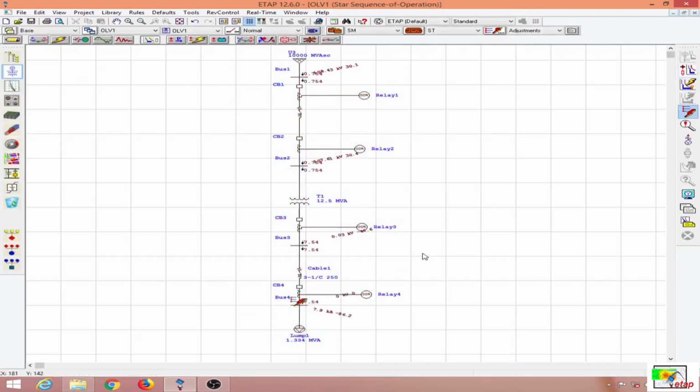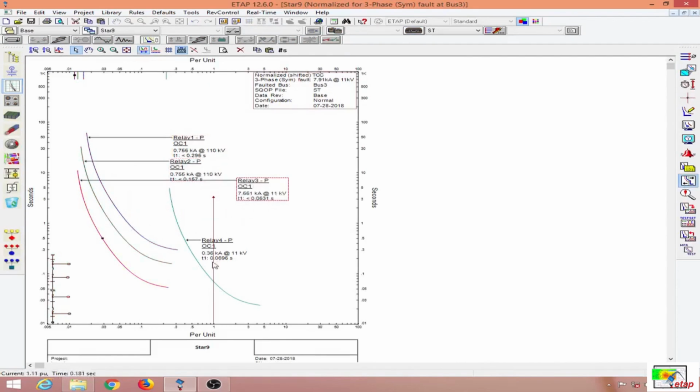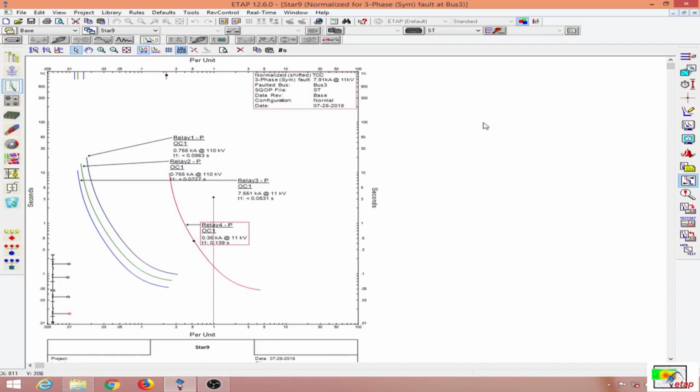Okay, then let us check this out again. Okay, everything is good for this case when bus 4 is faulted, and then we will perform the fault sequence insertion on this bus over here. This is bus number 3, and when running the sequence, okay, here we have a miscoordination, so we will go to the TCC curve and observe. Okay, now let us observe again.